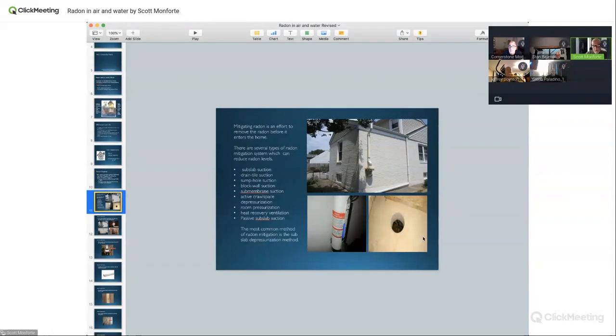If it's really wet, sometimes I'll go towards the center with multiple draw points. If there are multiple sump pumps and it's wet and it's always going to be wet, sometimes we have to go with 3, 4, 5 draw points, and we have to go into the center.